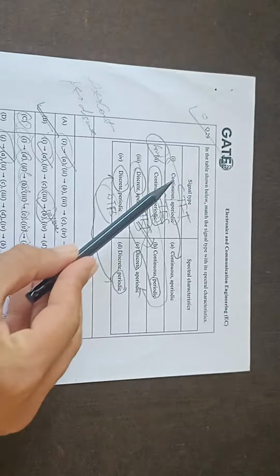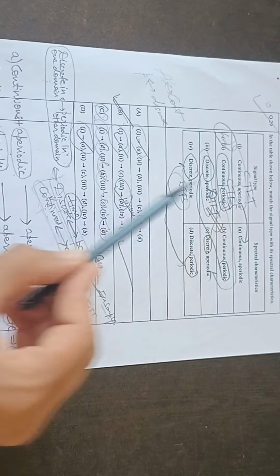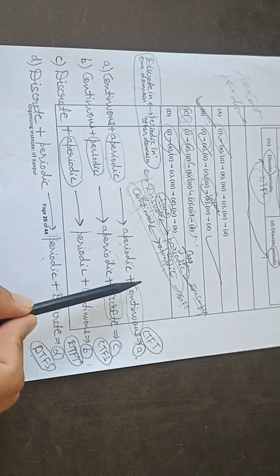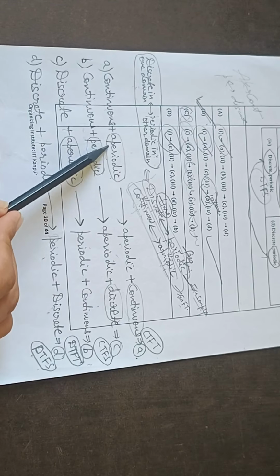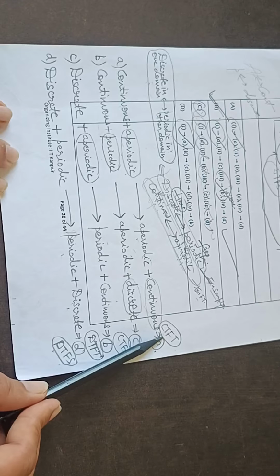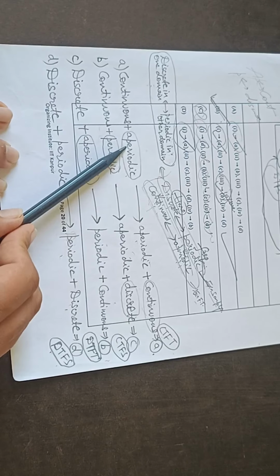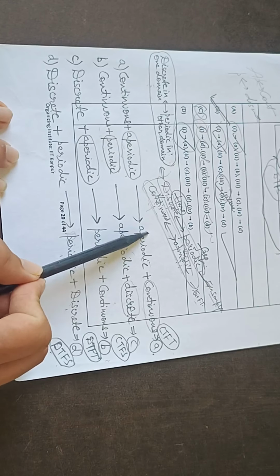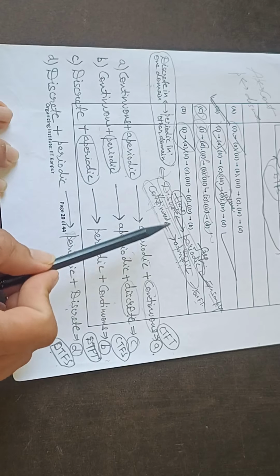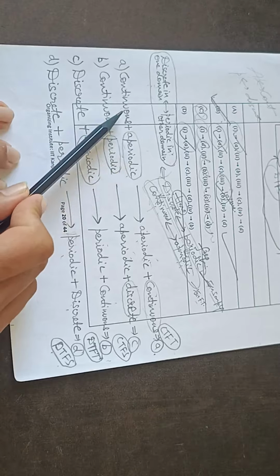So first is continuous and aperiodic. Continuous becomes aperiodic and aperiodic becomes continuous. So continuous aperiodic gives aperiodic continuous. This is the case of the continuous time Fourier transform, where the signal in the time domain is continuous and aperiodic, and the spectrum is also aperiodic and continuous. For example, rect(t) has a spectrum sinc, which is aperiodic and continuous, and rect(t) is also aperiodic and continuous.